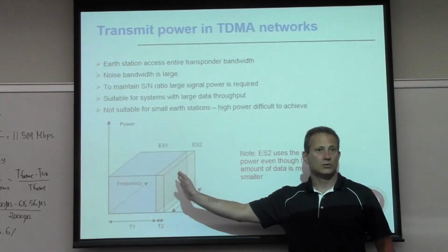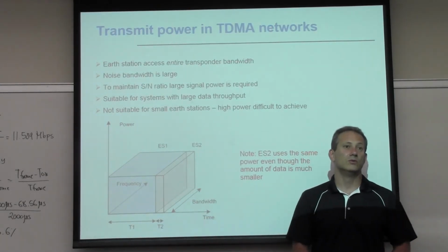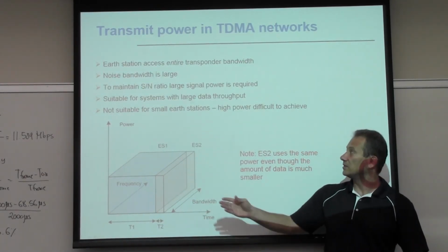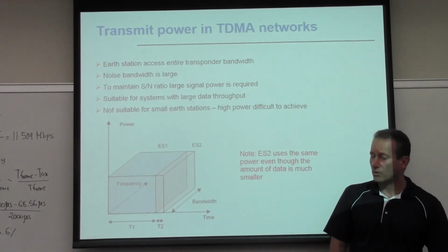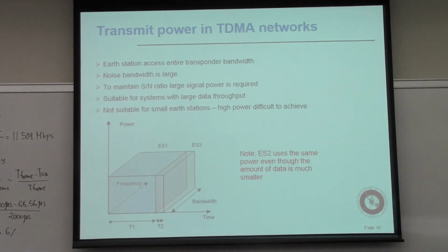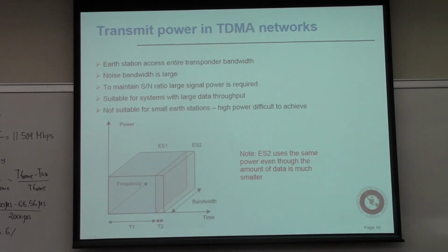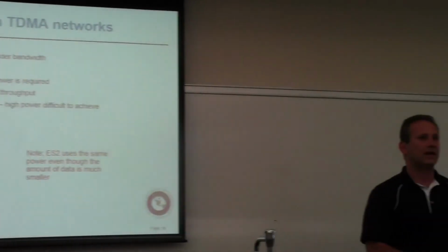And even though your transmission now is short, because you don't have much to send, you still have to use quite a bit of power. And for that reason, as I said, these guys require quite a bit of power, and they're appropriate for backhaul stations. Let's just work an example here. This is example 632 that calculates what this power is and compares what that power would be in the case of the FDMA access. And you can see that even though for many applications here on the ground, we have abandoned FDMA, right?